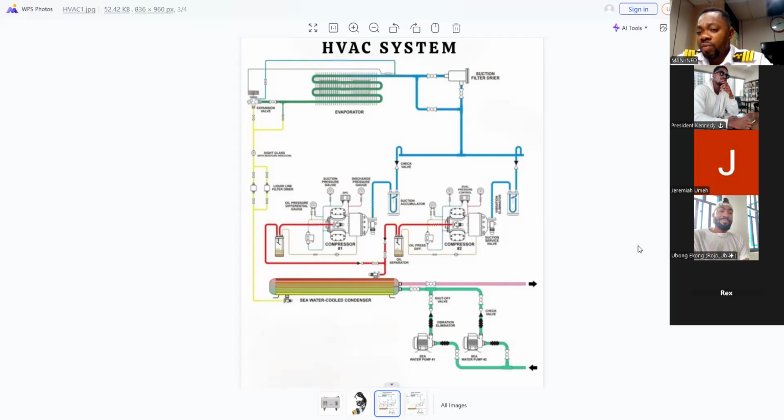So anytime you have flood back, it is probably because your evaporator blower is not working properly or not working at all, or your evaporator filter is restricted. So the blower fan cannot suck in air to pass across the coil to help it expel the coolness and change the state from liquid to gaseous.